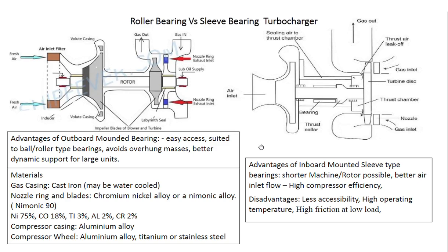You must have seen a side glass. The oil goes from the sump and is supplied to the ball and roller bearing. The side glass is provided for minimum and maximum oil level marking. The outboard bearing is lubricated by the main engine lube oil system through an independent pump. Either it can be from the main engine lube oil pump or through an independent system.